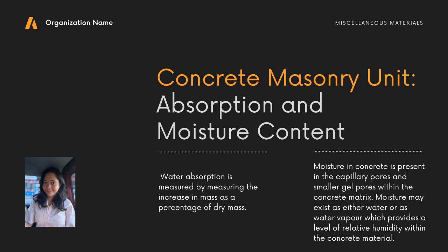Obviously, if the aggregates are in the surface wet condition, meaning moisture content is greater than the absorption, that surface water increases the water to cement ratio and affects strength and durability. Measuring and compensating for moisture in the aggregates is a critical part of any quality control process. If the means and method are not available to measure the moisture content of the aggregates, at least estimating by reviewing the stockpile is better than ignoring this input in the batch computer.